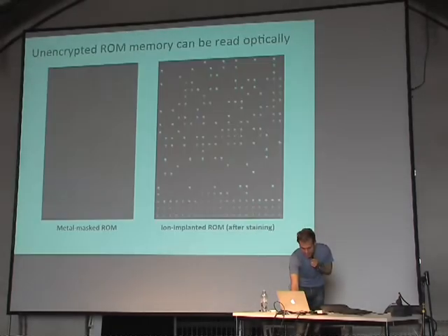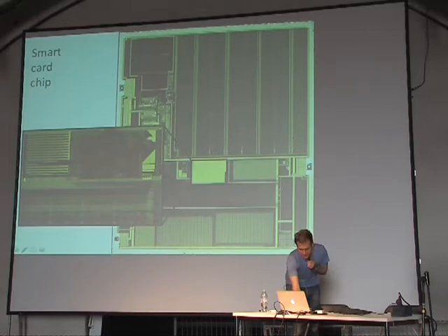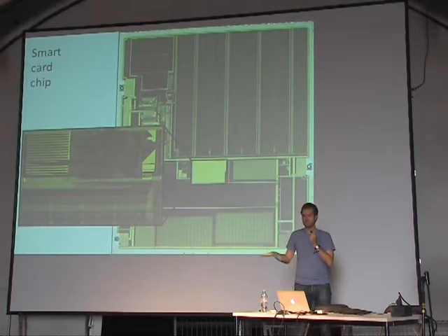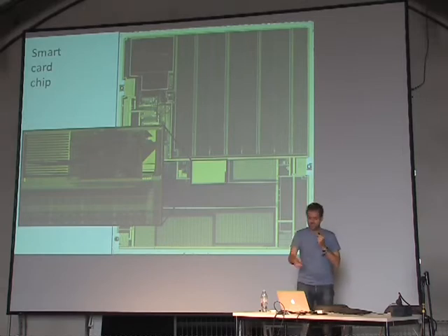The cost of a chip scales absolutely linearly with the size of the chip. So you have a certain cost per wafer, and the more chips you can put on the wafer, the cheaper every single chip. Meaning if you grow this by 10%, then the manufacturing cost is 10% larger.